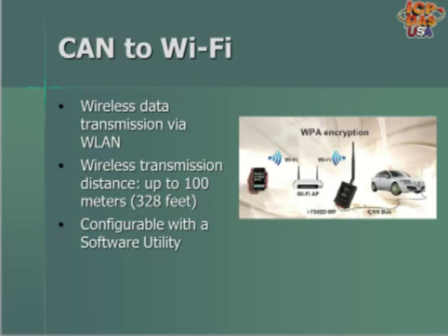Wi-Fi is a convenient and widely used wireless protocol. CAN to Wi-Fi converters like I-7540WF support communication distances up to 100 meters or 328 feet and allow devices like smartphones and laptops to communicate with CAN devices like controllers and data acquisition equipment, which may gather data like pressure or mileage. Wireless communication is especially ideal over wired when working with rotational machinery.